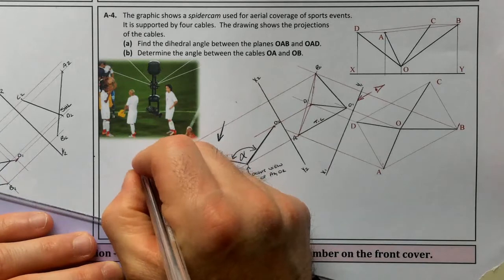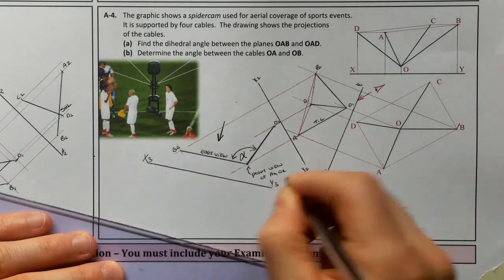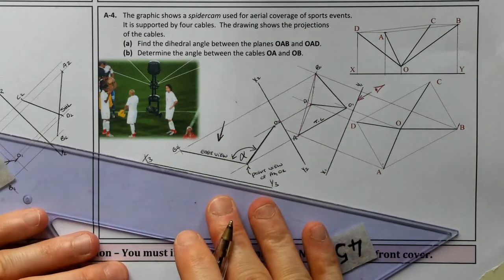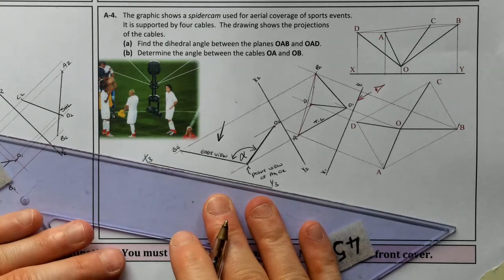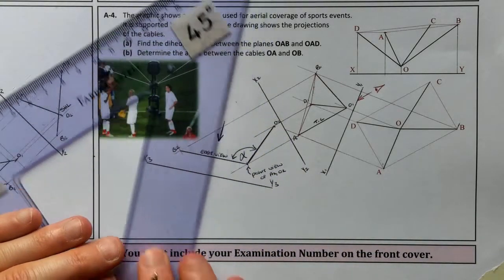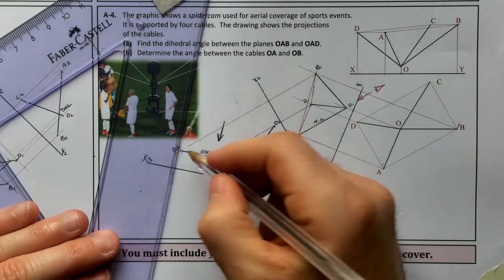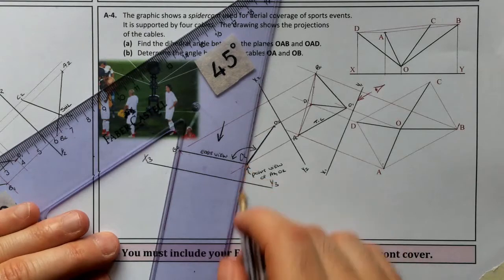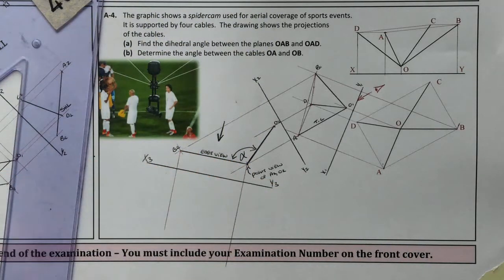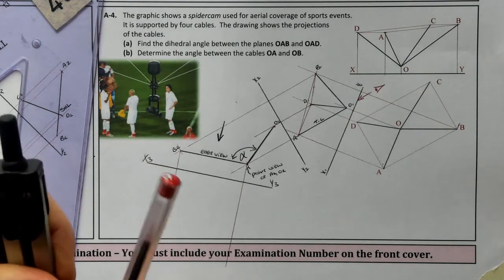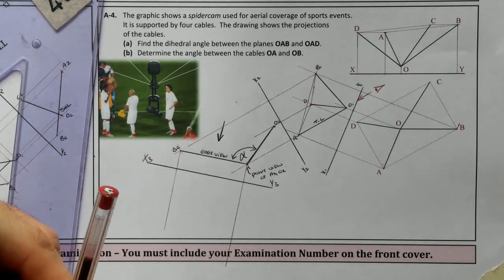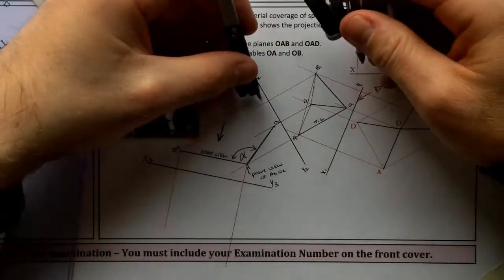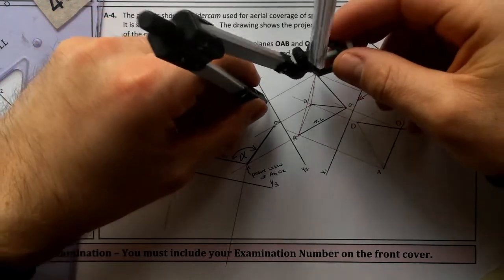So this is called an X3, Y3 here, and I'm going to set that up and project out once again perpendicular. I'm just projecting out two points here now. B is on its own, but OA, if you remember previously, was a point view there. It might have gone slightly off the sheet, doesn't matter. With my compass, same thing, you go to the previous XY line, which in this case is X2, Y2. So to find the distance for B, measure the distance from the X2, Y2 back to B.